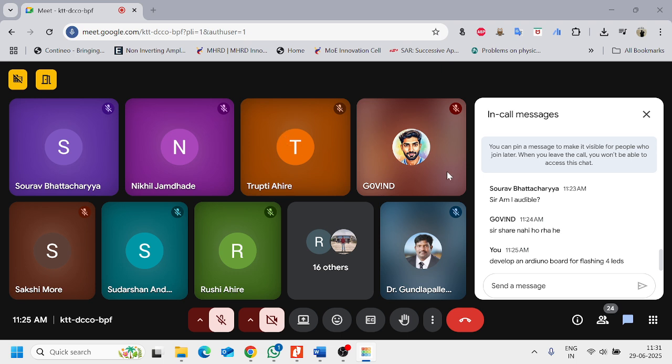I will read the value from the button, and I will say if it's equal to high, which means if button is not pressed, okay? Or let's say if button is low, okay? I mean if button is pressed, this time it's gonna blink both LEDs at the same time, all right?